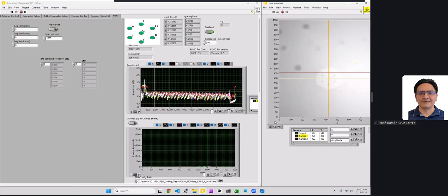This is all stuff that we catch if we use our ferrule press station correctly. Previously, when we were building the sensors for these setups, they're very precisely pressed, and they also have a rotational correction mechanism. By the time the sensor gets into the puck, the clocking should not change. It should just stay there unless something terribly goes wrong.